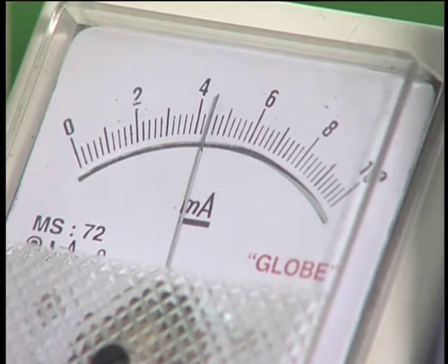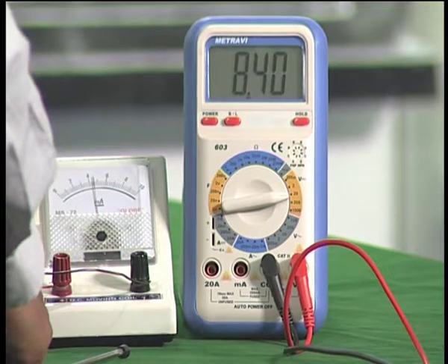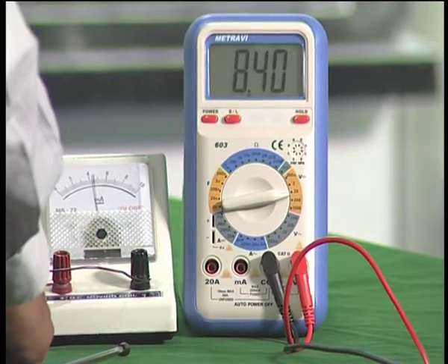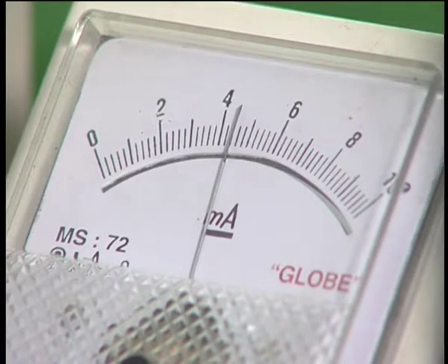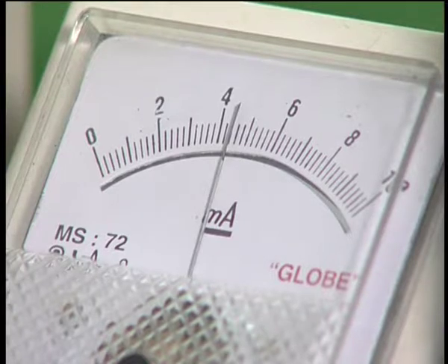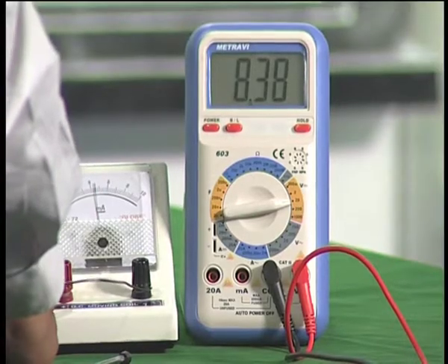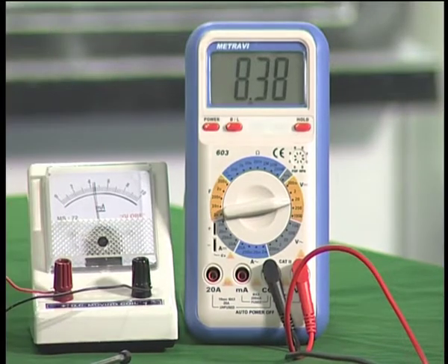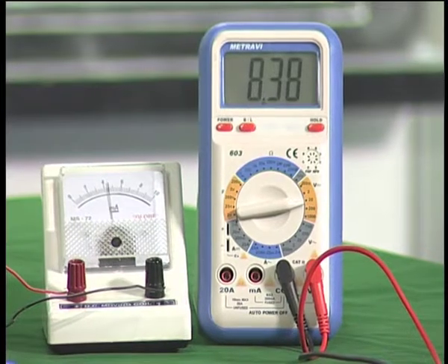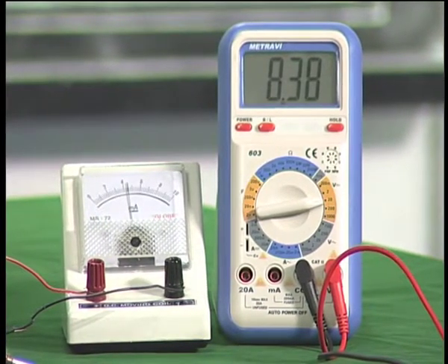I have almost come to 9 volts. Again in the meter, if you see the voltmeter, I am around 8.4 volts, but then the current is only 4.5 or something like that. So, you find the current is now saturating much earlier than what it was for minus 1 volt or for 0 volts between the gate and source. So, if I keep on doing it, I will be able to get all the different characteristics corresponding to different values of VGS, voltage between the gate and source.